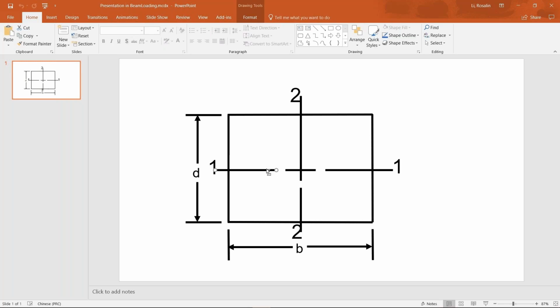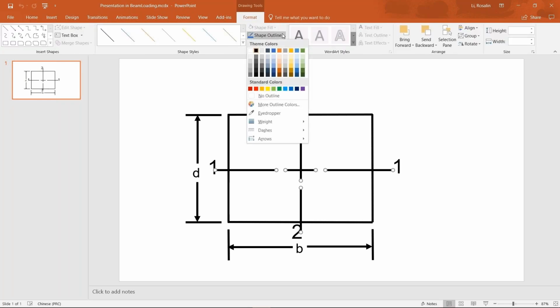It's an OLE container that allows us to double-click in the Mathcad space, and it'll automatically open up PowerPoint, Excel, Word, whatever you're making these drawings in, or whatever you have a spreadsheet in. You can make any edits and changes that you want, like we're going to do here in PowerPoint, and those edits can be pushed straight back into Mathcad. This means you won't be searching through your computer to find, oh my gosh, where is that PowerPoint file that I made this drawing in. It's automatically attached to Mathcad. You just double click it and it opens up for you.